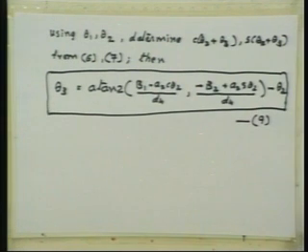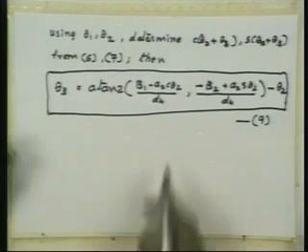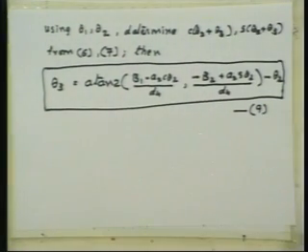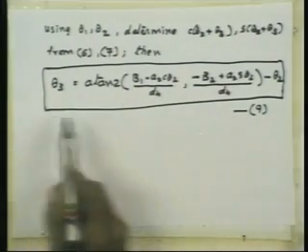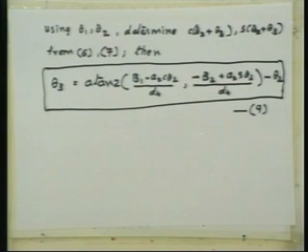How many solutions are there for theta 3? Yeah, from this expression just one solution. But if you go with the possibilities for theta 1 and theta 2, only theta 2 is occurring here, right? So how many solutions are there for theta 2? There are 4. So theta 3 will have corresponding 4 solutions. For each theta 2, you will have theta 3 obtained from this expression.